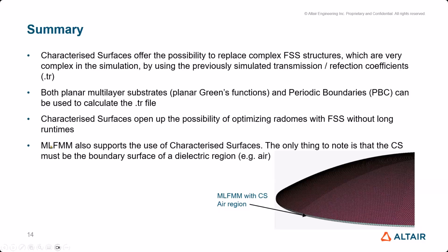Before I forget, MLFMM is also supported. When you want to use MLFMM with characterized surfaces, just keep one thing in mind: you need one dielectric region. So the CS structure must be the boundary between the dielectric region and the free space. Typically what I do is add a thin air region, and that should always work.